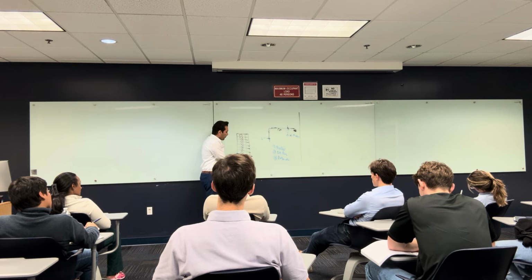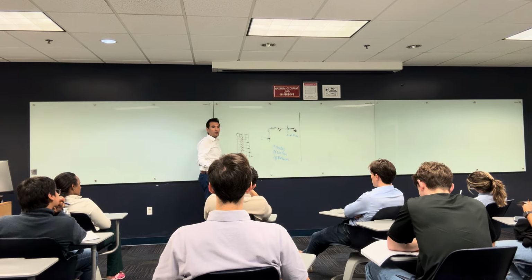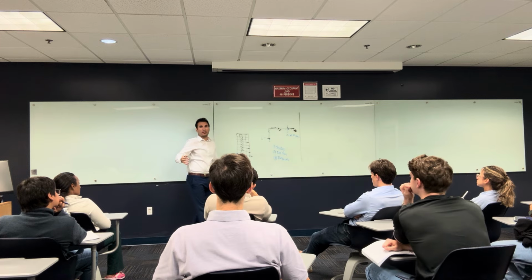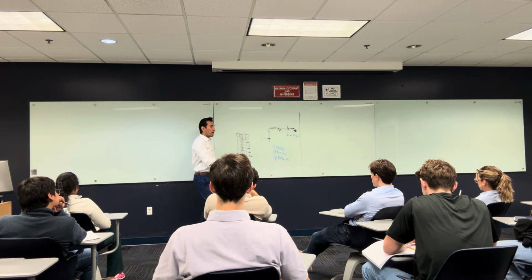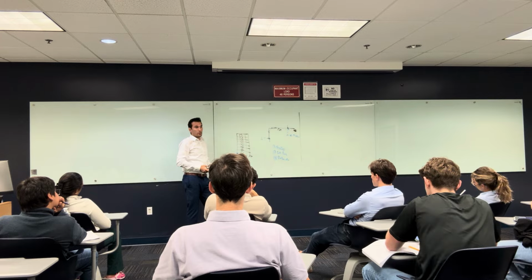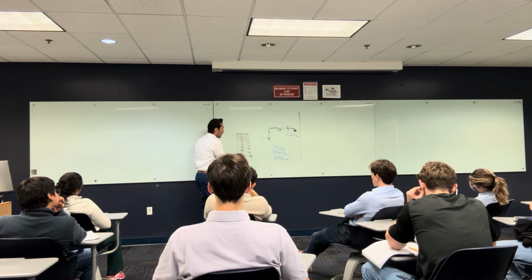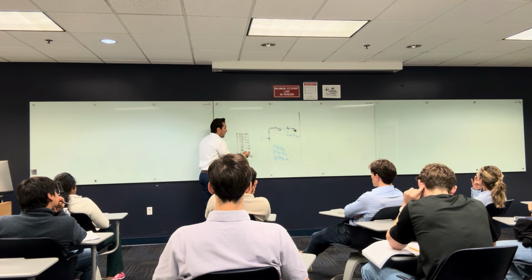Because bending, shear, normal and all the internal forces change from one story to another. But if you have 100 stories, you cannot design 100 sections. It's gonna be very expensive. You are gonna have the labor changing the formwork they pour the concrete in at every story. That's expensive. So that's why maybe you change it every 10 stories or something. Okay? All right. So you want to find all the internal forces.